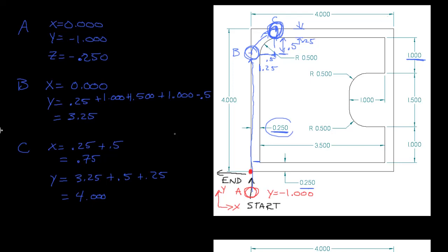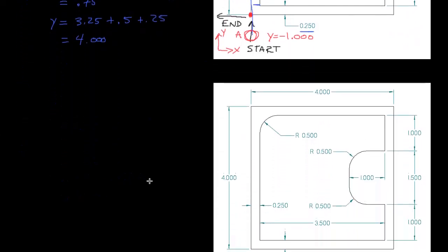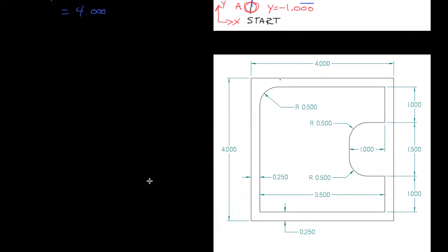All right, so then come back down. Maybe we'll start working off this one. So we have point C right here. Here's my cutter. The center is right there. Nice that this is a 1/2 inch cutter in diameter, because we have a 0.25 inch step over all the way around. So I know that the center of the tool is going to ride along this 4-inch block here. All right. So I'll just put a point here where my G54 work offset is. So this is x equals 0 and y equals 0, just to keep things consistent.